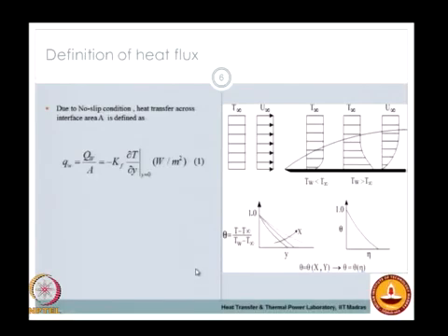The good thing about this flat plate boundary layer problem is that it is very interesting and more fundamental when you develop what we call similarity solutions. If you define a non-dimensional temperature theta and plot that, you will find this non-dimensional temperature is a function of both the x coordinate, that is your axial distance along the plate, as well as the y coordinate, or the height across the plate.